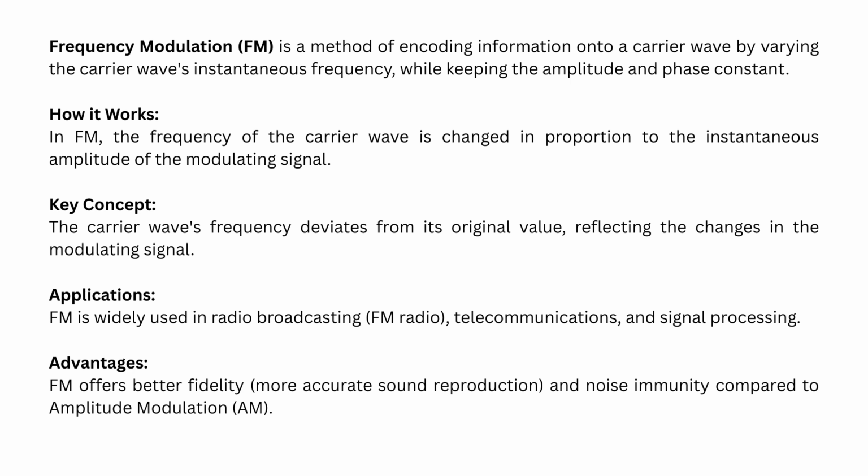Along with that, its cons are the larger bandwidth requirement. FM signals use more bandwidth, which can limit the number of stations. So there is a limit for the number of stations also. The broadcast range is also a little bit shorter. When you compare FM with AM, FM signals typically don't travel as far. So these are the cons of FM.